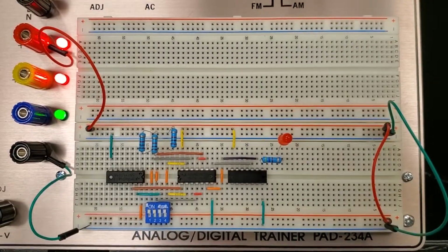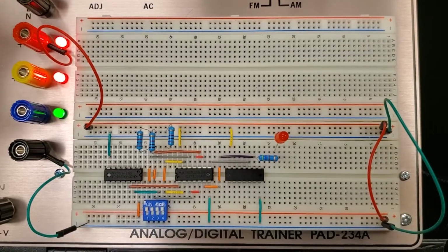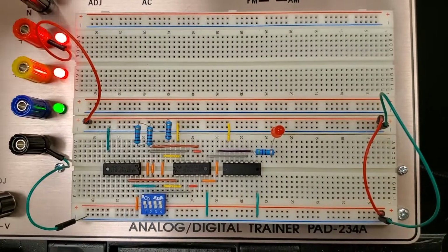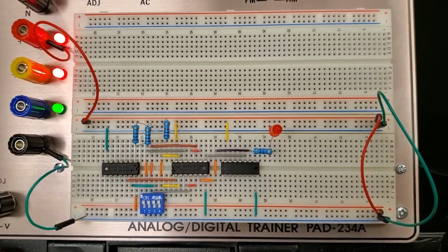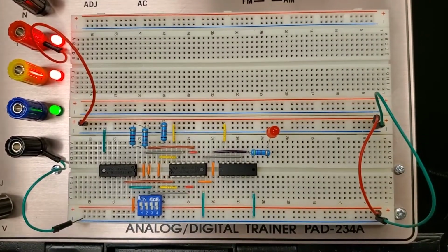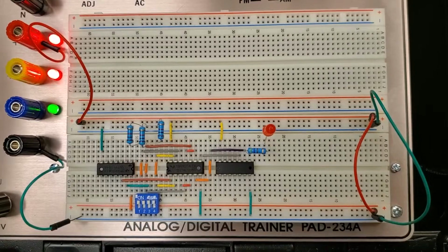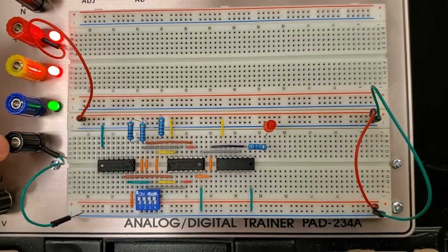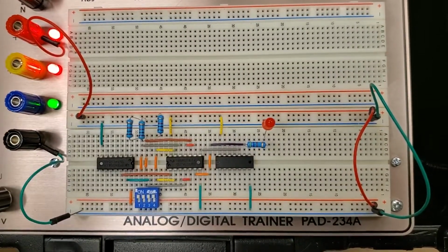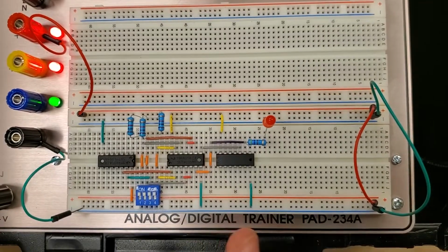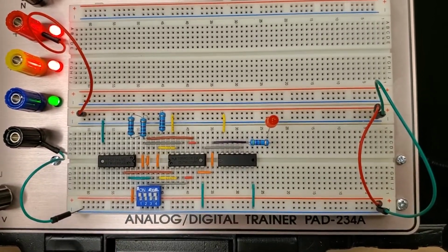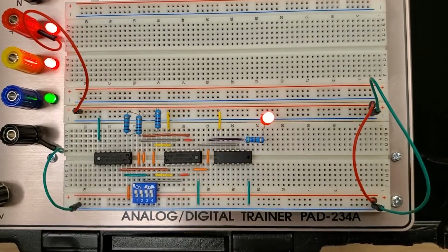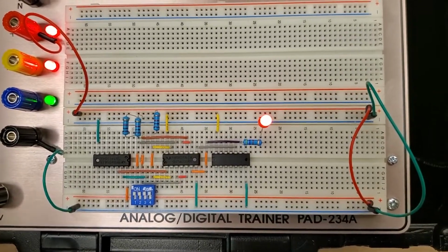So a bug we were given for a circuit was a loose connection to ground. How we fix this, we asked some very good questions of what we were doing when it stopped working and if you heard anything. He said he heard some vibration, and that could be a sign of a loose connection. He also noted that he tried to tighten this ground terminal. Once we took a closer look at it, we realized that the ground was not actually having a good connection, so it was not giving us an output even though all of our inputs were high. So when we take that ground and put it back in so it's got a solid connection, our output comes back on and our circuit is working perfectly fine again.